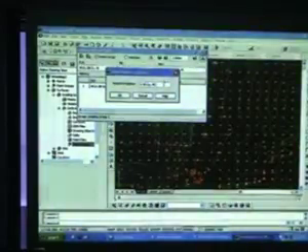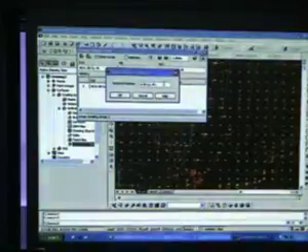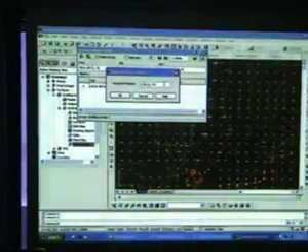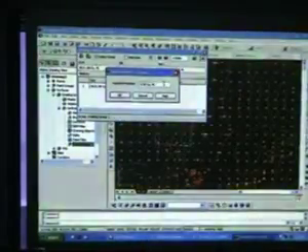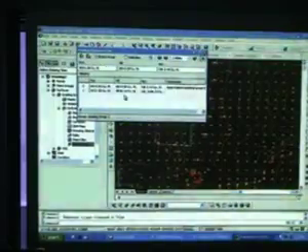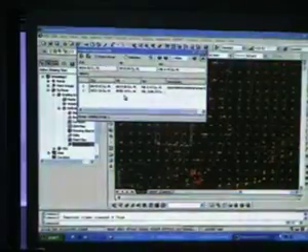Okay, so if we want the cut and fill to be equal to each other, the required volume you type in as 0, so it's equal. If you want more fill, you put a positive amount. If you want more cut, you put a negative. So let's say we put it at 0. I'm going to click OK. So then it automatically adjusts it for me.